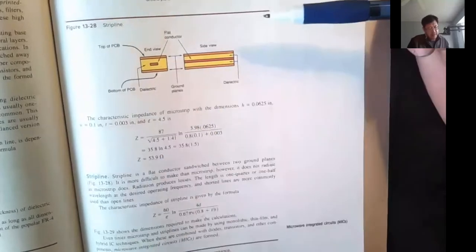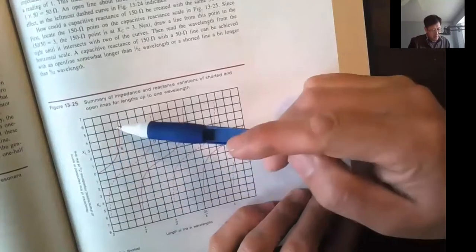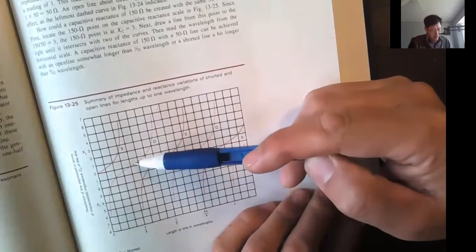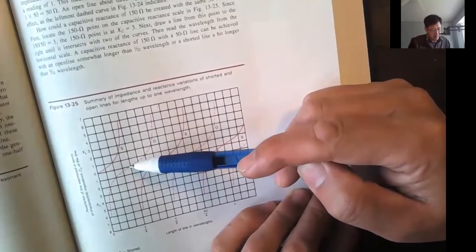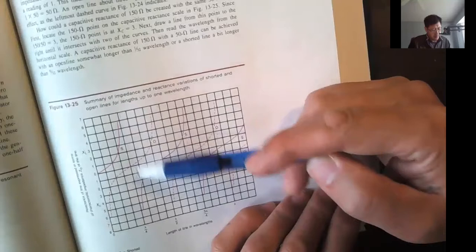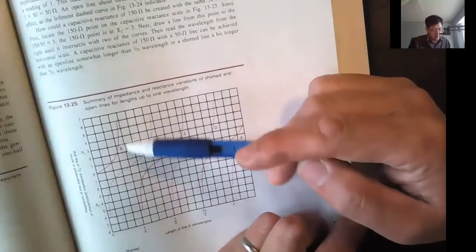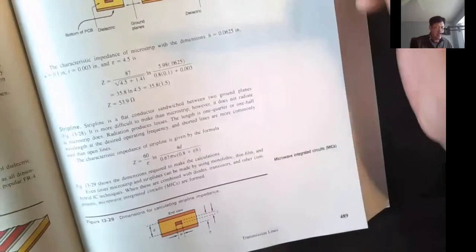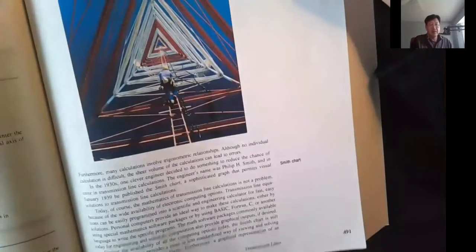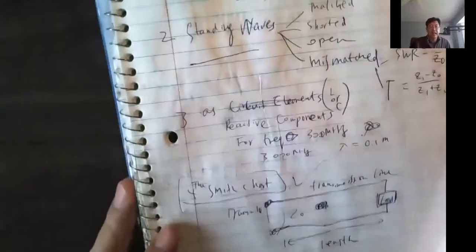And by controlling the length of the transmission line, we can make that transmission line an inductor, a capacitor, inductor, capacitor, or at resonance, at 0 ohm. This is called a parallel resonance. This is called a serial resonance. So as an inductor and capacitor in parallel, or inductor and capacitor in serial resonance. So you can use that transmission line as reactive components. Instead of building inductors and capacitors, all you need is a little strip of wire printed on the circuit, and use that little strip of wire as the tuner or as the filter, as a reactive component.